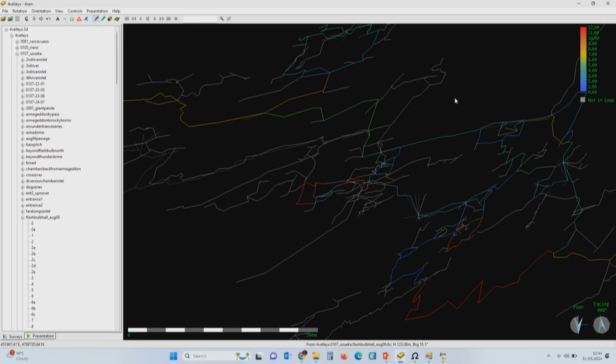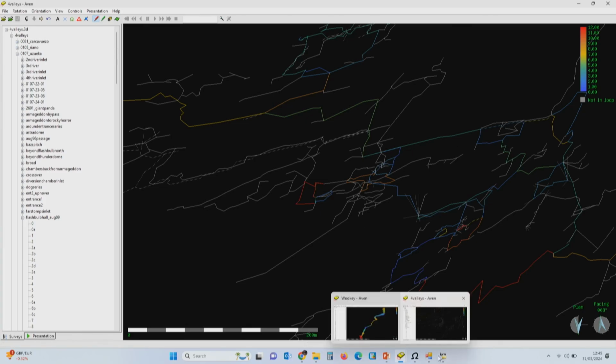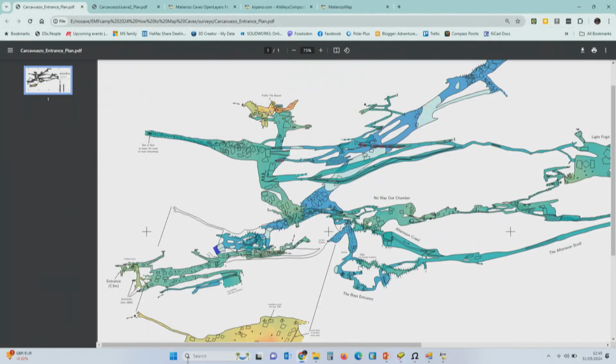The problem if you've drawn your 60 kilometres of cave beautifully up in Inkscape, and then someone closes a loop or finds a new entrance and we GPS that and it shifts everything, then that least squares process pulls the backbone of the cave to a different position to what you've drawn. So Cave has developed drawing packages, like vector drawing packages, where you attach your vector drawing to the backbone, and it produces these sorts of beautiful maps that you can see here.